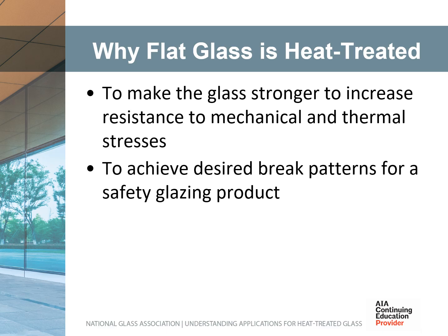The most commonly used process for heat-treating architectural products calls for the glass to be cut to the desired size, transported through a furnace, and uniformly heated to approximately 1150 degrees Fahrenheit. Upon exiting the furnace, the glass is rapidly cooled by blowing air uniformly onto both surfaces simultaneously. This process is known as quenching.